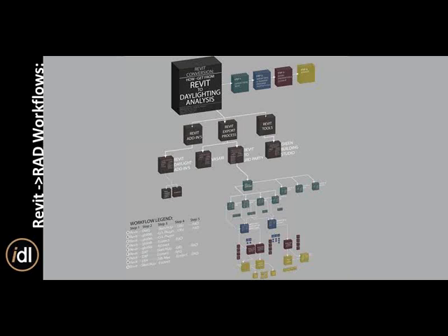Exporting from Revit, do worksets come into play? So if you turn off elements within Revit that are on a workset, do those export anyway? I don't know if we tried that, Lauren, but it takes that 3D view, whatever you can see in that 3D view, it exports that. So if you turn on and off different worksets, different layers, whatever, it's whatever you're viewing in that 3D view. Yeah, so there could be a whole protocol: if you're working within someone's Revit model, you don't want to delete things or turn off certain things. You can create your own analysis view that you would use as the export view to get some of these objects out.